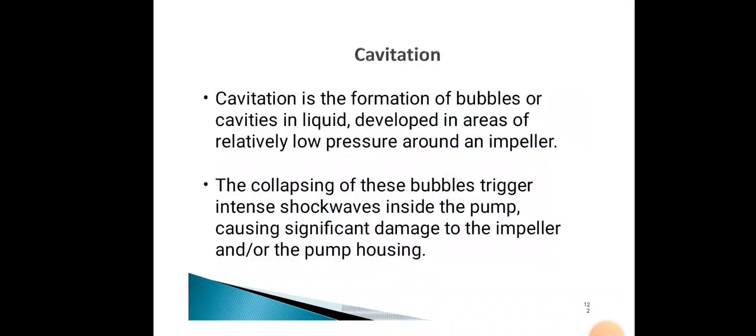Cavitation is the formation of bubbles or cavities in liquid developed in areas of relatively low pressure around an impeller. The collapsing of these bubbles triggers intense shock waves inside the pump, causing significant damage to the impeller and or the pump housing.